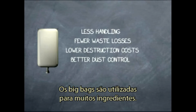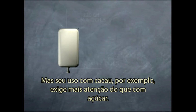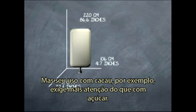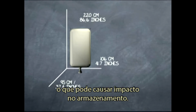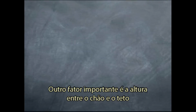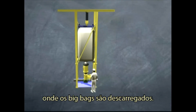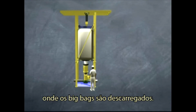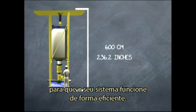Super sacks are used for many ingredients. Cocoa in super sacks needs much more attention than sugar, for instance. The standard bag size is high because powder is bulky. This may have an impact on the storage facilities. Equally important is the height between the floor and the ceiling where super sacks are discharged. There are many more details that need to be reviewed to make your system work efficiently.